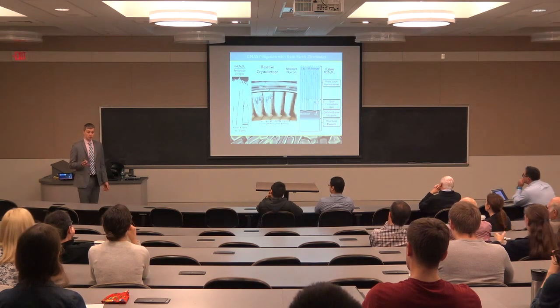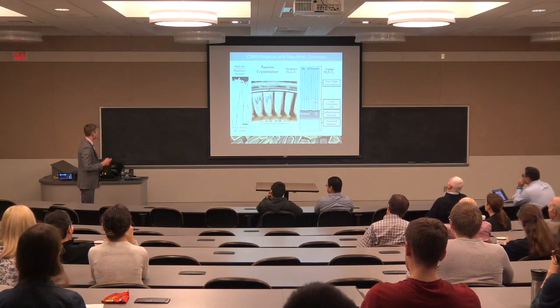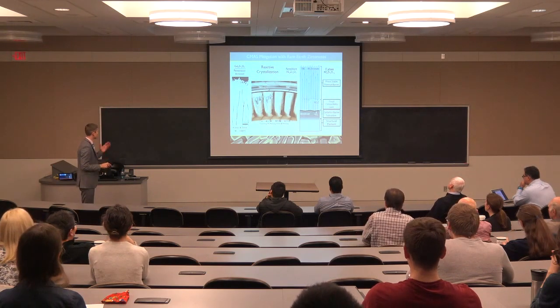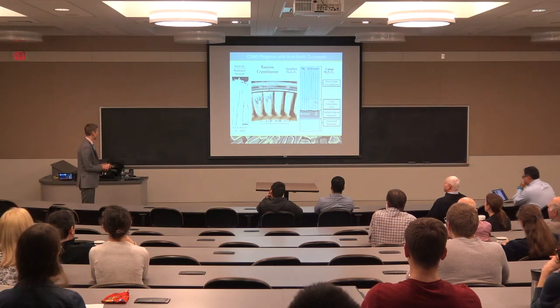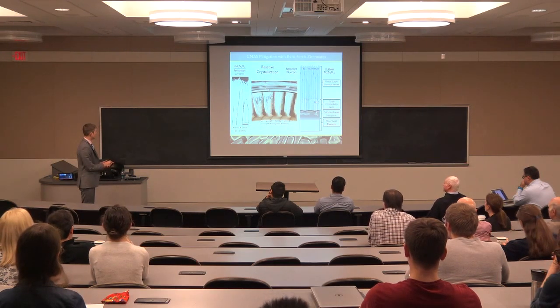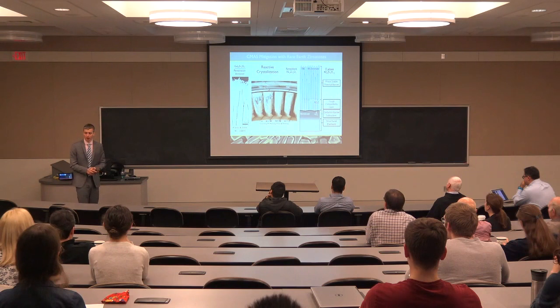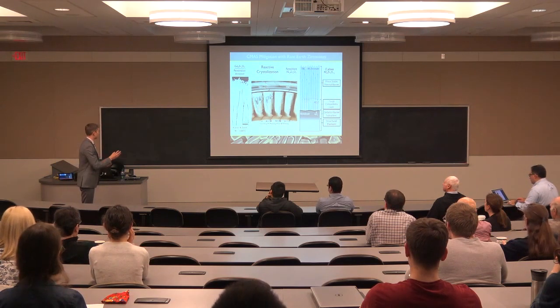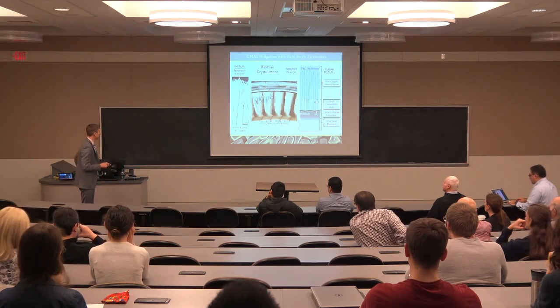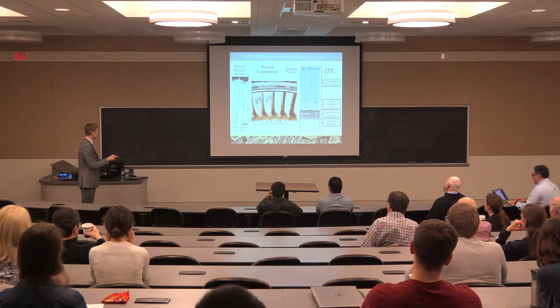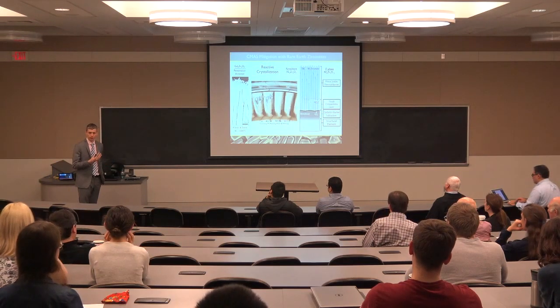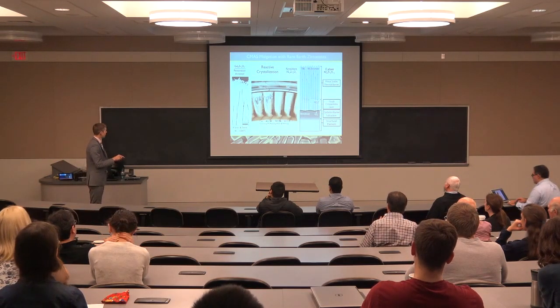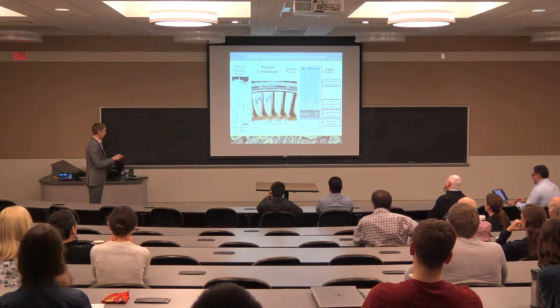But the process doesn't work equally well. Rather, I should say here, so this process works. So this is an example from a jet engine, a Pratt & Whitney engine, where these are our turbine blades that had the conventional coating on them. They flew in a harsh service environment, probably an airline operated in the Middle East, where there's a lot of sand coming into the engines. And this coating, these big regions are places where there's bare metal exposed. The entire coating has been lost. The coating on these blades is this gadolinium zirconia.